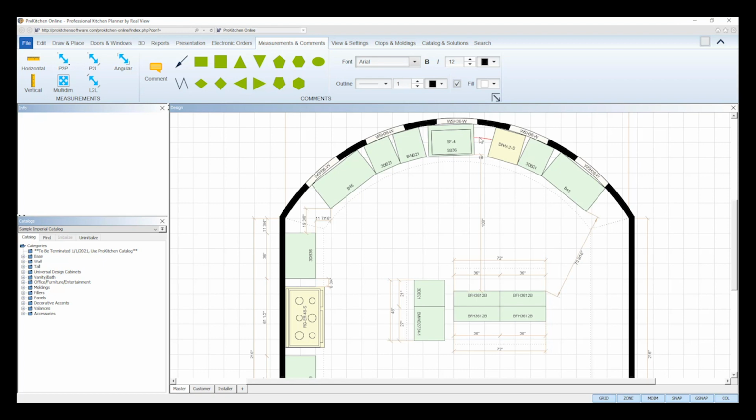Dimensions can easily be hidden or deleted after being placed. Simply select the Delete tool from its right-click toolbox and it will delete that selected dimension. If you select the Hide tool from its toolbox, it will hide the selected dimension on the current view only. It will still be displayed on your other views unless you set it otherwise.